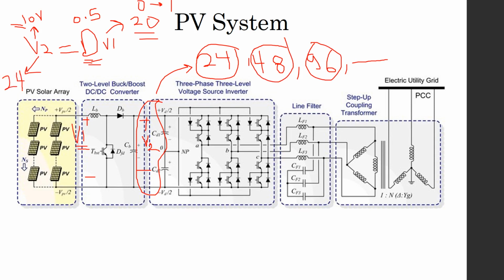Now what happens here? By using the buck converter, or the boost, which is the step up DC chopper, or a buck boost. Buck boost does the two functions, buck or step down and boost converter. Now for example, inside the buck converter, this V2 is the output here connected to a battery. This value is a constant. We cannot change this voltage. Now by using the duty cycle, we can control the V1, which is the output of the PV array.